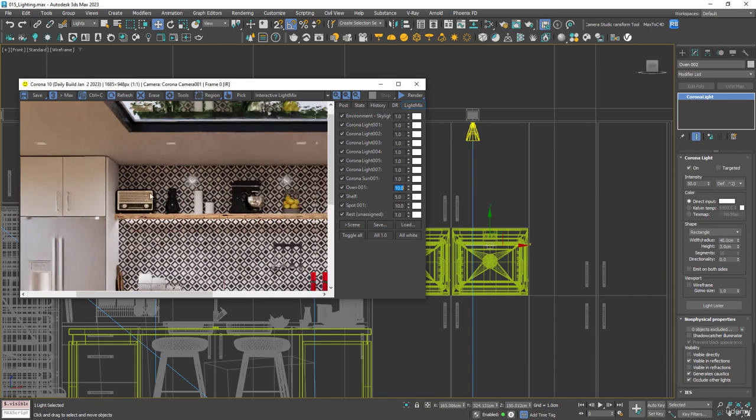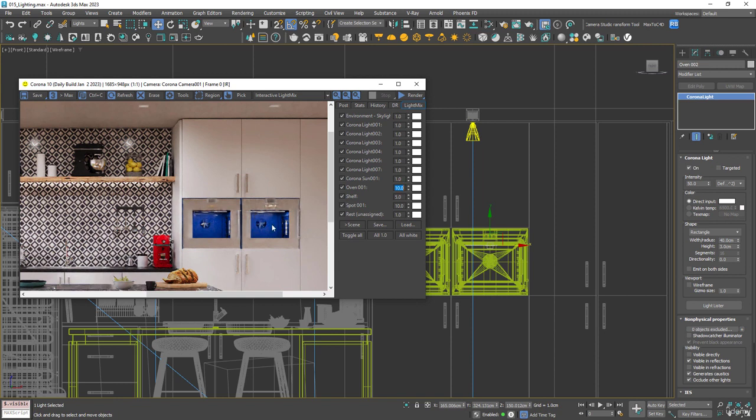And before we do another render, I'm going to change the material to black from blue. And also we can add a color to this light. And if you're ever changing colors of artificial light, it's really worth using Kelvin temperature, as this is what we use in the real world. If you bring that up, you'll see that goes blue. And if you bring it down, it will go more orange. So I think something like 3500 here will give a nice warm light in that oven.